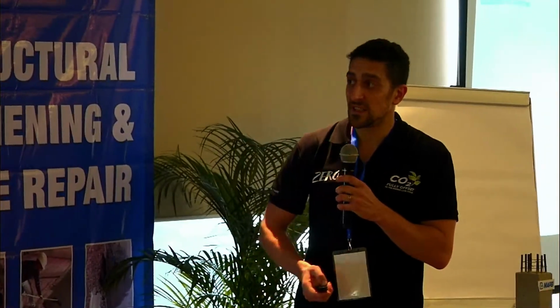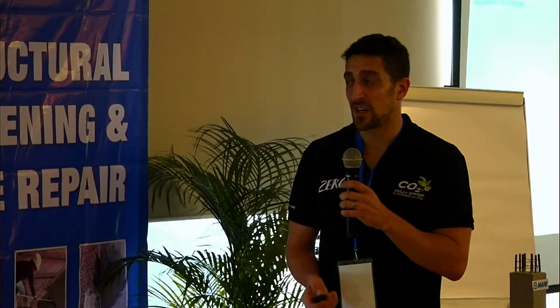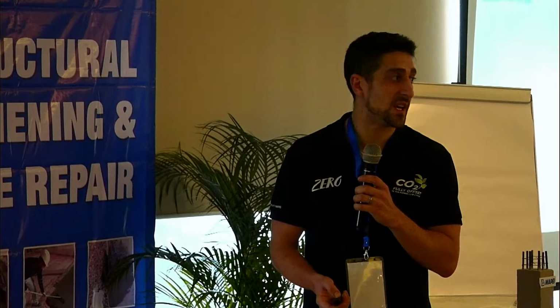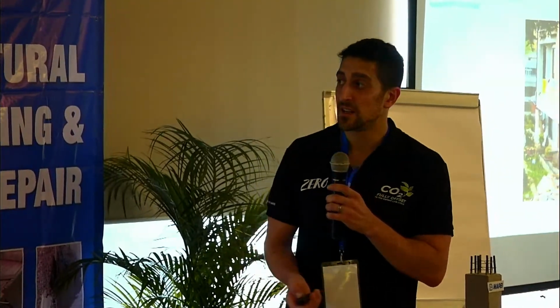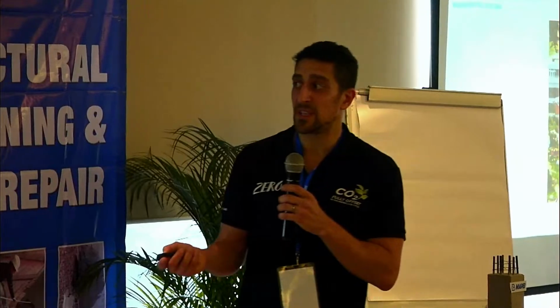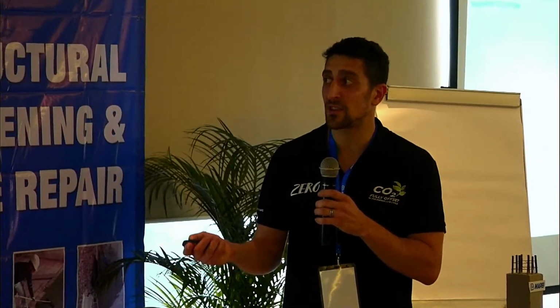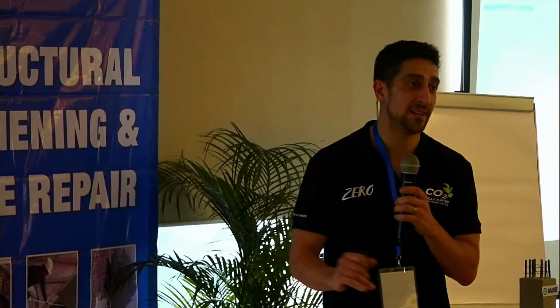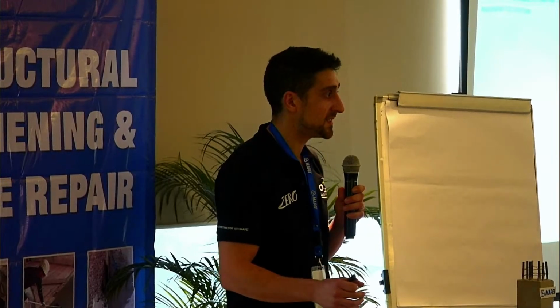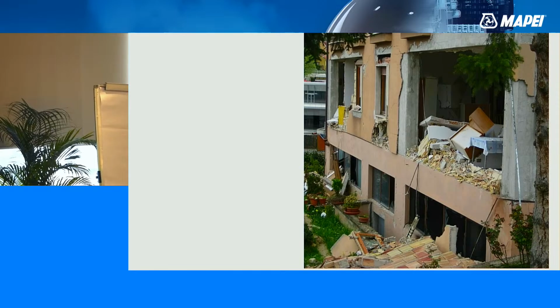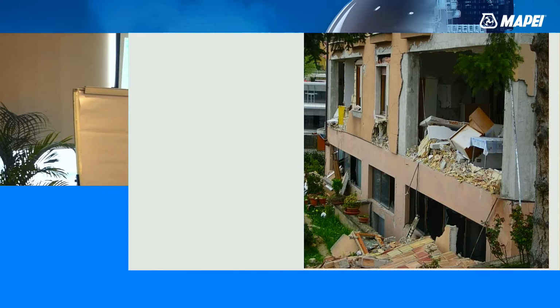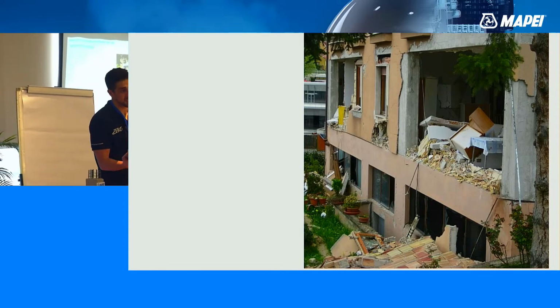This is a mechanism really common during an earthquake, and I think that even in Indonesia something like this can happen. It could happen that the reinforced concrete elements are completely undamaged, without cracks, but all the infill walls can be damaged and overturned, out of plane or in plane.